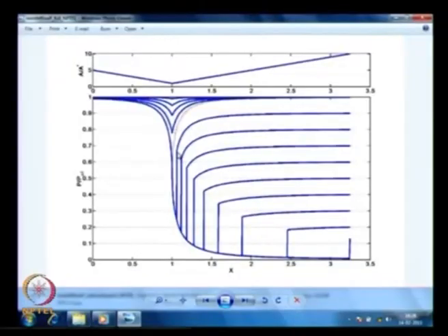It so happens that from here to here there is a huge pressure jump. I am at say 0.24 or something. It is going all the way to 0.67 or so. And here if I look at it, let us find the numbers there, 0.25 and 0.68 or something like that. It will be of the order of 2.3 or so, P2 by P1. Let us say I go here, I will pick a nicer number. Let us say I will pick this one, this is 0.1 to 0.5, P2 by P1 is 5.